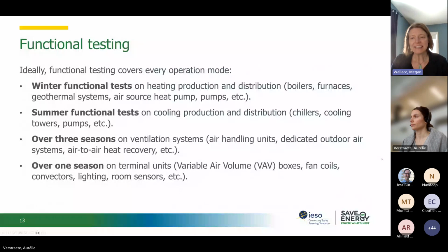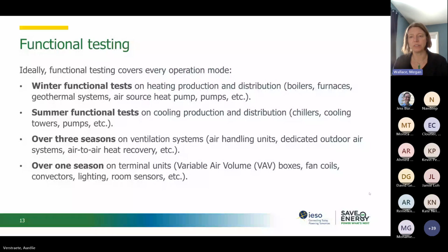Ideally, functional testing covers every mode of operation. You're going to want to do winter functional testing on your heating systems, which would include boilers, furnaces, geothermal systems, air source heat pumps, and any circulating pumps related to that. You'd want to do summer functional tests for your cooling systems.